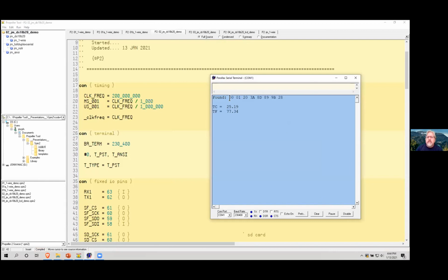So this, again, is the serial number for my device. Now, this number at the end is what's called the family code. So that's what tells me it's a DS18B20. This is the serial number, and this is the CRC. So that combined is the entire one ID. And we can see this should be activated. I can see the temperature changing now that I grabbed it.